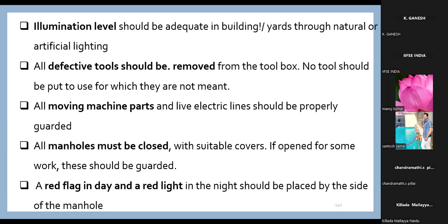For excavation work, you see a flagman or the banksman holding two flags. But if we have an excavated area or deep excavation, then we use red lights at the corners of the perimeter of the excavated area. This is a flickering light that uses solar energy. In the day you can put the red flag, but in the night it is mandatory that you go for red lights.